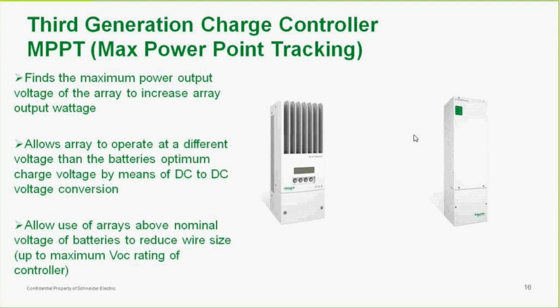So if we look at a nominal 12-volt module, it puts out about 17 volts open circuit, and its max power voltage, or VMP, is tailored to be above the desired battery voltage on a hot day. So, for instance, a 12-volt module might have a VMP of 15 or 16 volts, which is above what you'd want to charge a 12-volt battery.